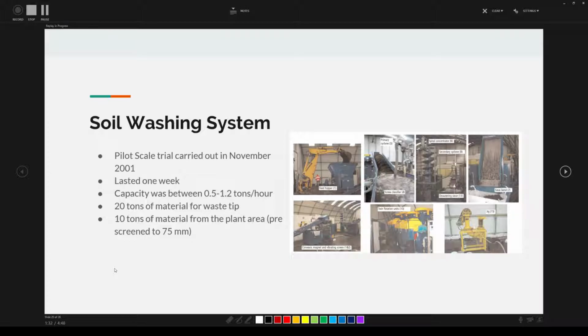So the electromagnet removes iron-based debris, and the weighing cell and conveyor belt with speed control controls the feed rate to the process. Additionally, water sprayed vibratory screen at 2 millimeters apertures disaggregates the soil and removes the oversized fractions.